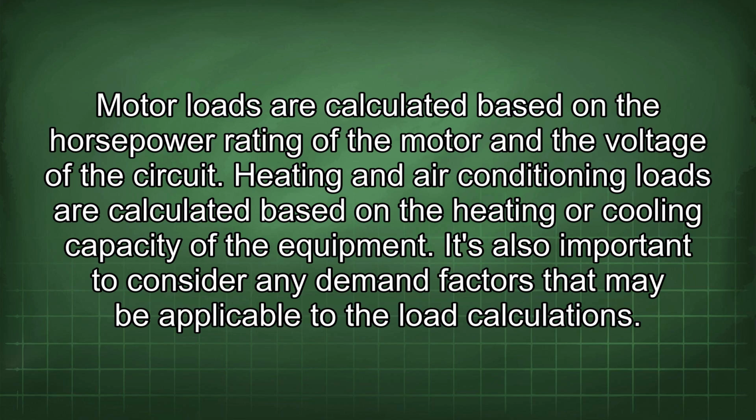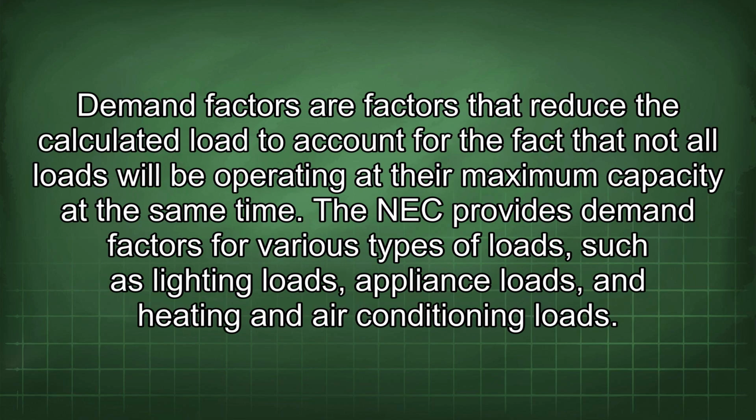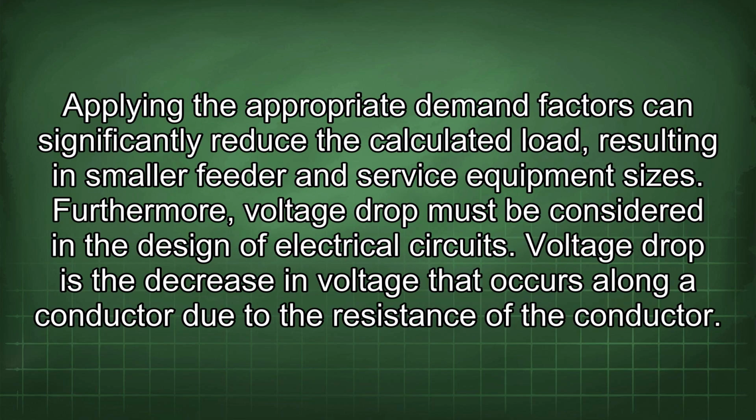It's also important to consider any demand factors that may be applicable to the load calculations. Demand factors are factors that reduce the calculated load to account for the fact that not all loads will be operating at their maximum capacity at the same time. The NEC provides demand factors for various types of loads such as lighting loads, appliance loads, and heating and air conditioning loads. Applying the appropriate demand factors can significantly reduce the calculated load, resulting in smaller feeder and service equipment sizes.